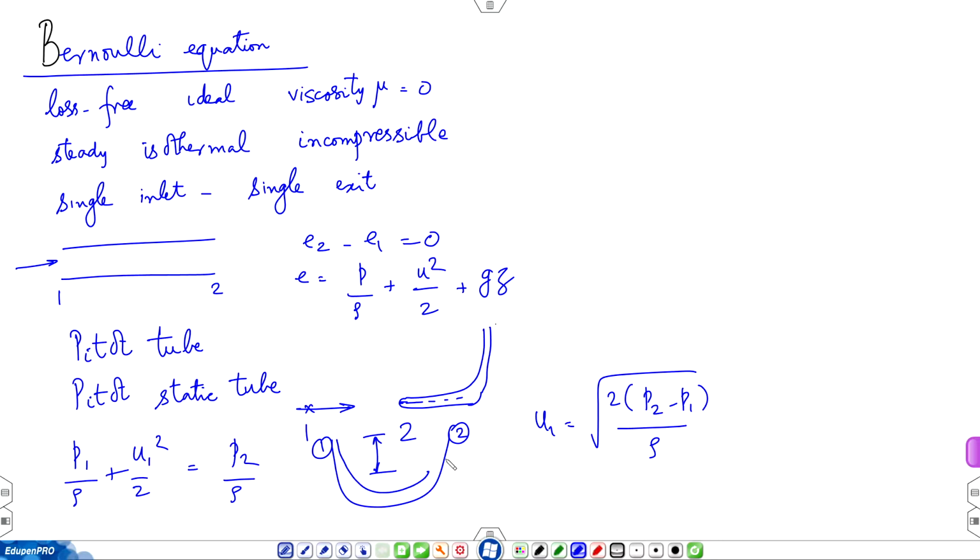If you remember the wake deficit method, there was a velocity deficit in the wake using which we found the force acting on the object. Now, how do you measure velocity? One possibility is to use a pitot tube. So, this tube is placed, you have to move it in the wake and measure the velocity distribution. Okay. So, this gadget becomes a useful approach to measuring velocity.